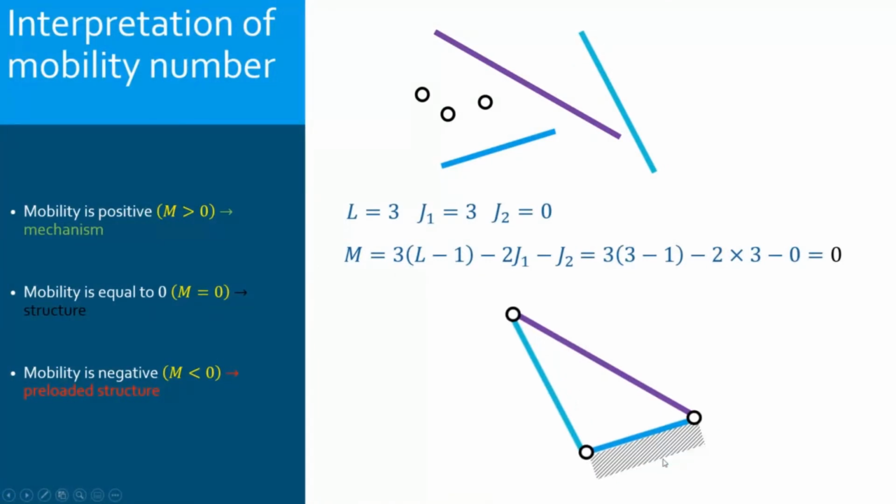And now, if I fix the ground, there is no possible motion. You cannot move the other two bars. It's impossible. The degree of freedom is 0. That's why, for example, in metallic structures, metallic bridges, the Eiffel Tower, there is plenty of use of this triangular structure. Why? Because this one does not allow any relative motion.